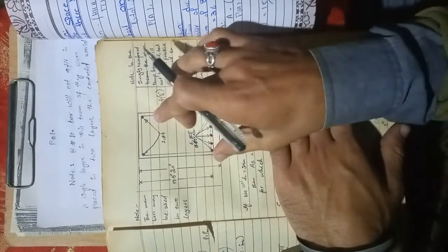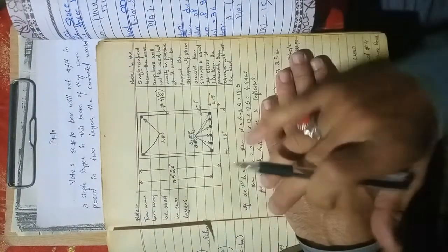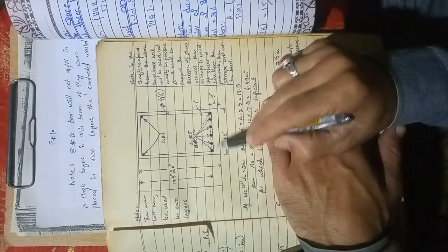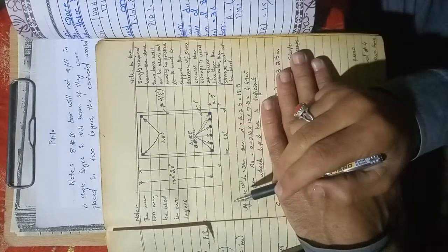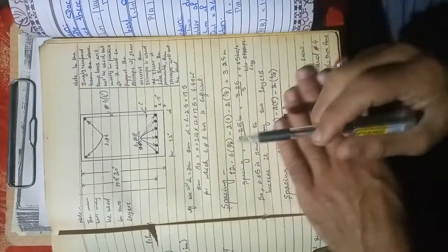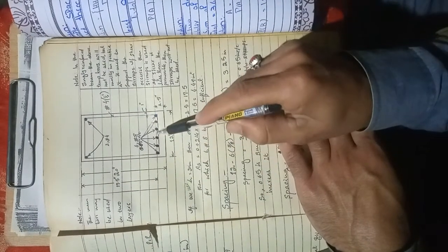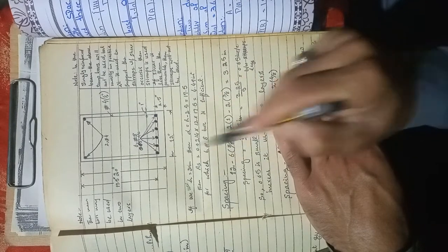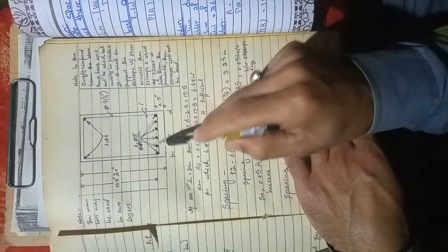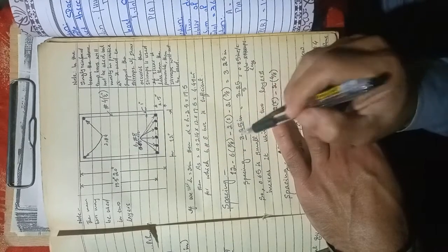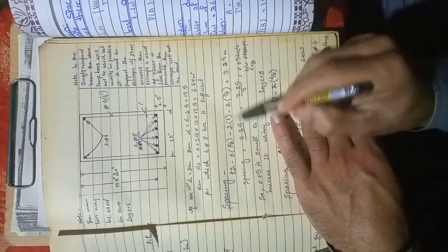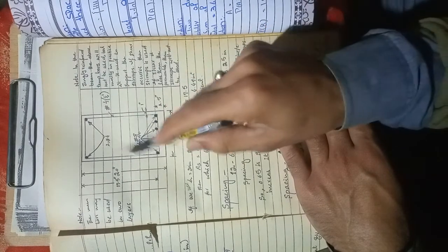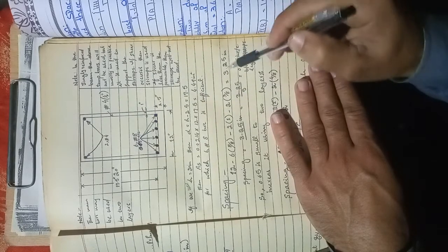I have designed a singly reinforced beam. You can see this is 20 inches, and the effective depth is 17.5 inches. We placed 6 number 8 bars right here. So when we calculate the spacing between these bars, this is the 12 inch width, minus 6 times 8 by 8, the total linear distance covered by these bars, minus 2 times 1 inch for the clear cover, minus 3 by 8 for the stirrup, right? So this gives us 3.25.